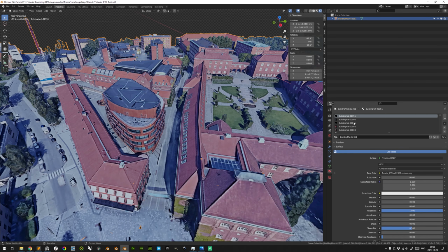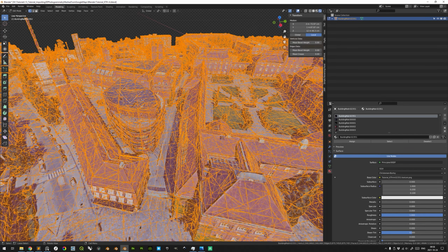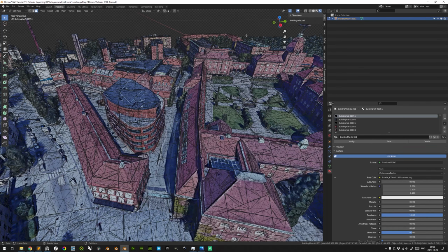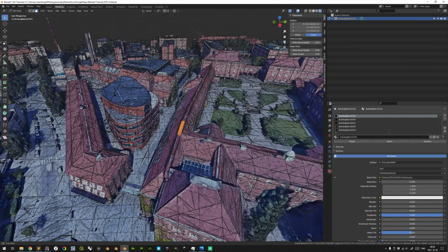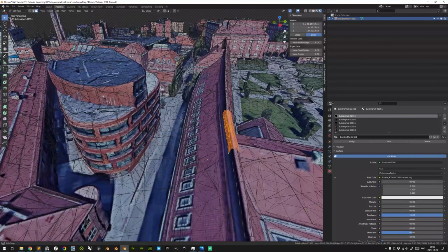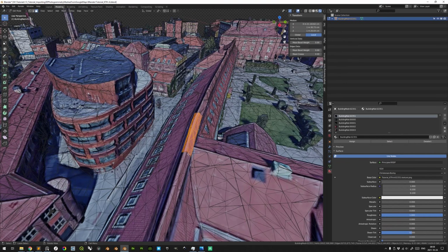And we want to make sure that we only have one material, because now if we enter edit mode here with the Tab key, and select face selection mode, and press Alt A to cancel the selection, we can see, with this first material in the list selected, and if we click select here, we will select in the scene. Yeah, and that was, of course, the object that we chose as active. So that's the root object for all of these merged objects.